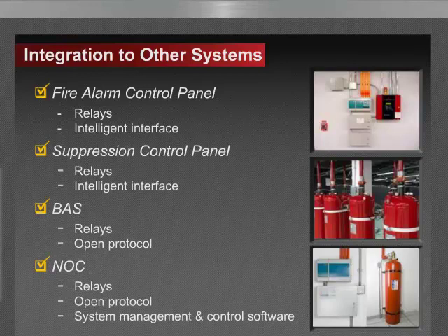Normally, it's recommended that in that case, where you're monitoring multiple air handling units off a single pipe, to branch the pipe and have individual branches, so you're not creating that Venturi effect with holes going across one air handling unit and on to the next one. So that's very important. And also consider dilution.